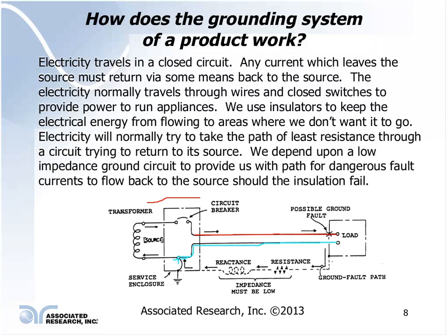Notice it's also connected to earth ground here, okay? So we have our ground connection, tying this neutral back to ground here, giving us our grounded neutral return conductor.